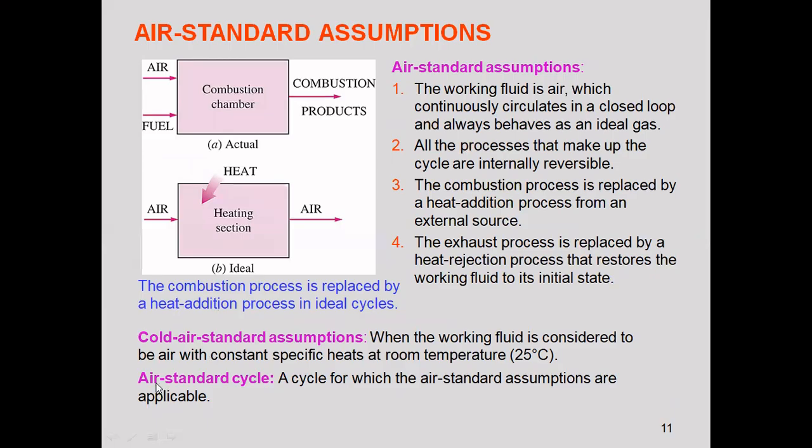They are called air standard cycles because the working fluid is assumed to be only air, with no fuel. But gas power cycles actually involve an air and fuel mixture initially before combustion, and after combustion that will be the product of combustion, which will undergo the expansion process and exhaust process, etc. But the air standard cycle is a simplified version of the actual cycle.